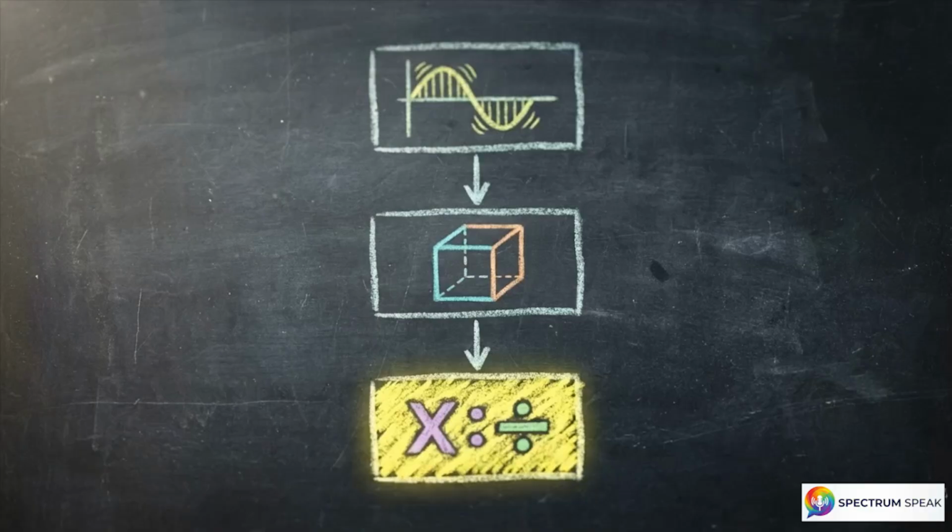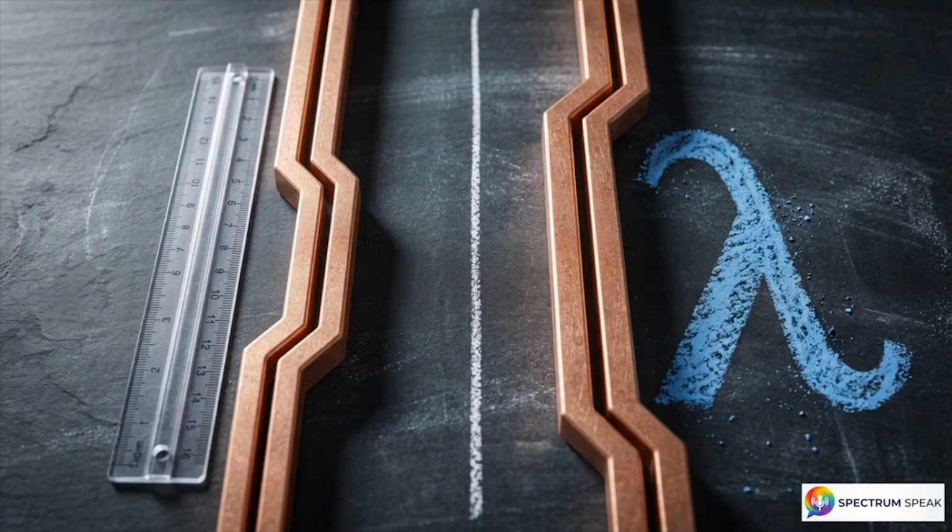This dictates an actionable workflow for all future designs. First, check your frequency. Second, check your dielectric's relative permittivity. Third, calculate the length-to-wavelength ratio. Physical size is an illusion. Only by calculating electrical dimensions can engineers prevent signal integrity collapse and survive electromagnetic compatibility testing.